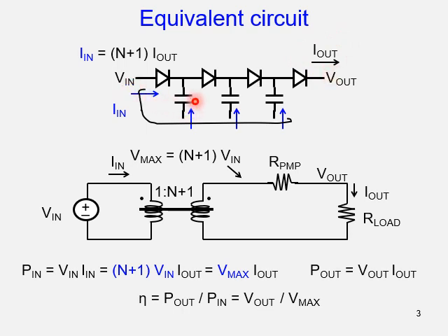Similarly, the individual driver to drive each capacitor must input the same amount of current. Because the number of capacitors is now n, a total of n plus 1 current paths the charge pump circuit has. As a result, the total input current is expressed by this equation. This doesn't consider any parasitic capacitance component in the circuit. This just considers the intrinsic term at this point. And this equation can be modeled using a transformer like this.